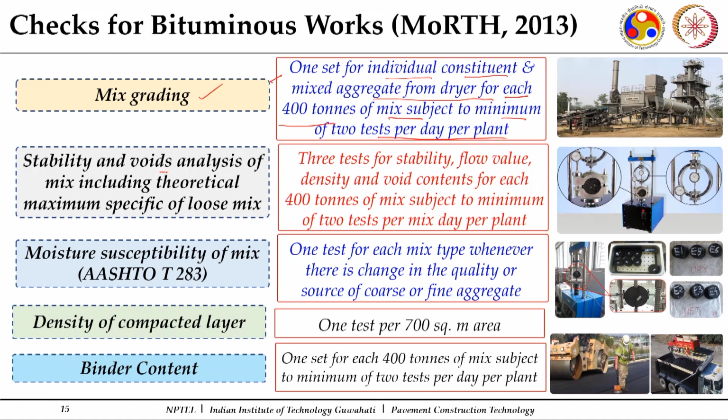Then regarding the mixes, specifically stability and void analysis of mix, including theoretical maximum specific gravity of loose mix. Simultaneously for this particular mix, the loose mix can be taken and ensured for the theoretical maximum specific gravity. It can be compacted in the laboratory again with the binder content, with the gradation which is available, and to see what is the stability which we are getting.